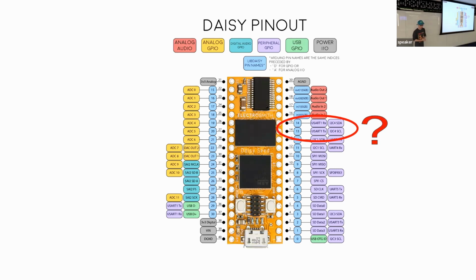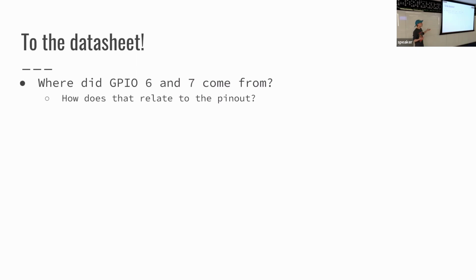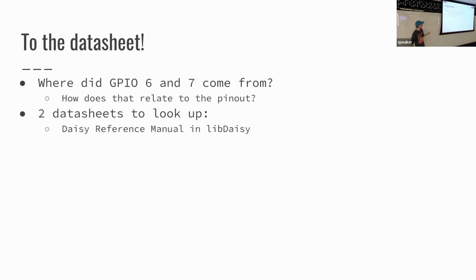This is a thing that trips a lot of people up when they start, and it's just good to know ahead of time that it'll be a problem, or not a problem, just something you have to figure out. The names of pins can be a big pain, figuring out what you actually connect your wire into, and what you reference in the code. That'll be probably the first place where you're like, I plugged the MIDI in and now it's not working. Go to the reference manual.